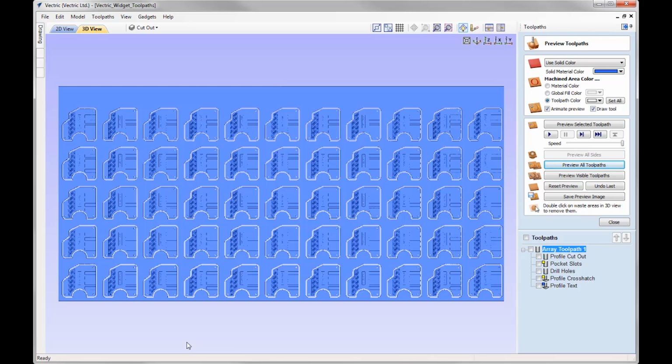Now, if we wanted to minimize the tool changes, where for instance in our example we wanted to run all of the toolpaths that use end mills to begin with, followed by all of the toolpaths that use the V bit, then we can go back into the form and use the option to minimize the tool changes.